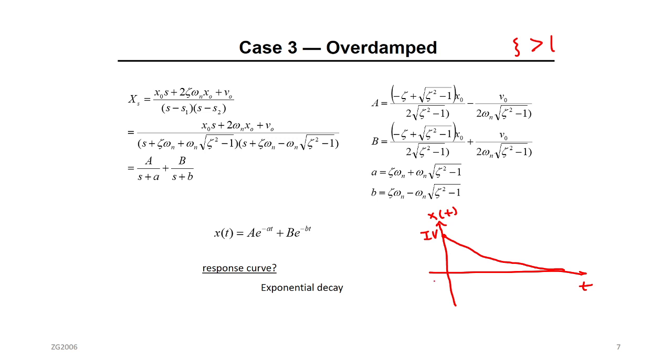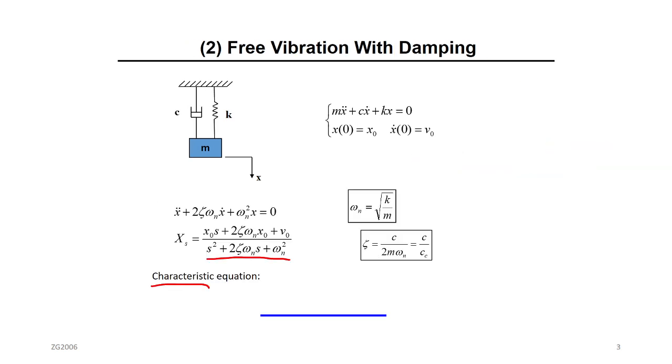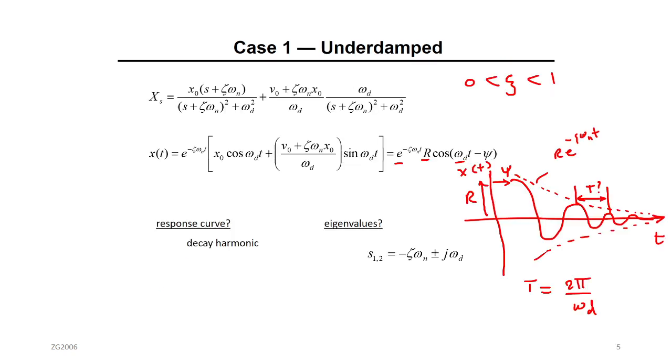All right. And these are all the cases that you can see for any second order system. There are no more cases. Any second order system will behave similar to one of these four cases. If you have no damping, it will be similar to this one. If you have damping, then you check your damping coefficient. If it's underdamped, then this is going to be the transient response.